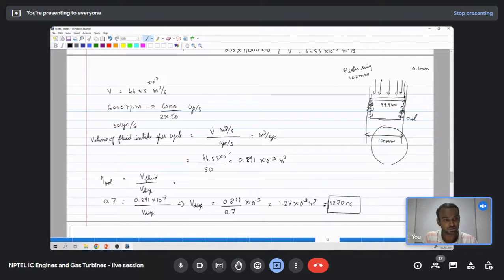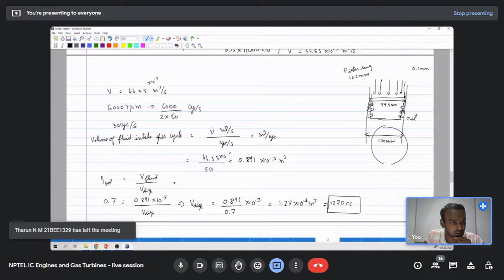When the oil goes into the combustion chamber and participates in combustion, we get a lot of HC emissions and smoke. To avoid that, we have the oil ring, and the first two rings prevent the gas from coming downward. Heat dissipation, indirectly it has an effect, but its main purpose is not heat dissipation.